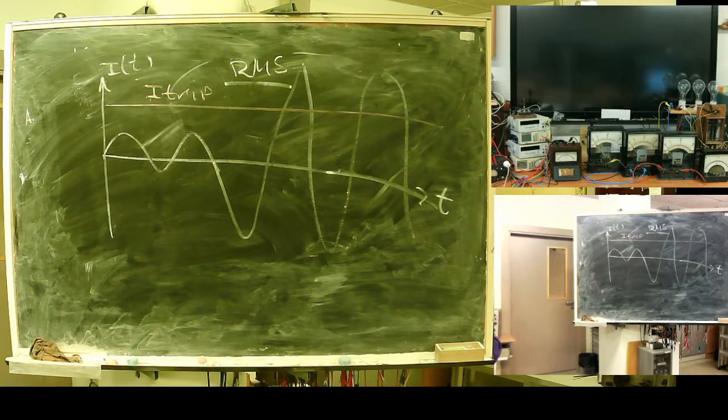If you connect this to your AC circuit and some DC circuit to the resistors of same value, DC current producing as much heat as this AC current will be its RMS equivalent or effective value.